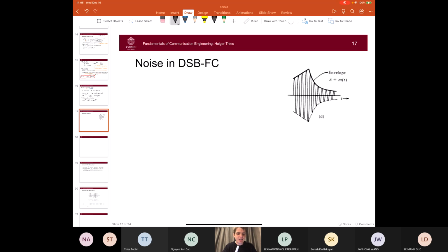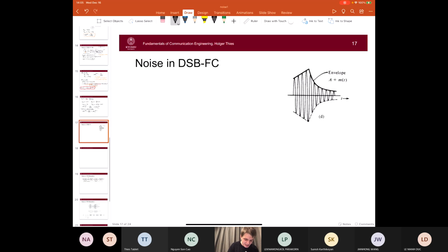So what we can do then, instead of doing the coherent reconstruction, which means just applying the modulation scheme again, is a different form of demodulation, which is envelope detection. And recall the envelope of the carrier signal was just the peaks of the amplitude. We have seen that if the modulated message that we send does not intersect the x-axis, so if it's always larger than 0, then we can use envelope detection for demodulation. And an envelope detector can be implemented quite cheaply. So all we have to do is reconstruct the envelope of the signal we send in the demodulation.